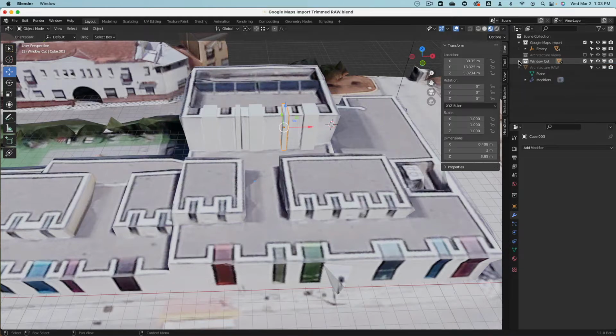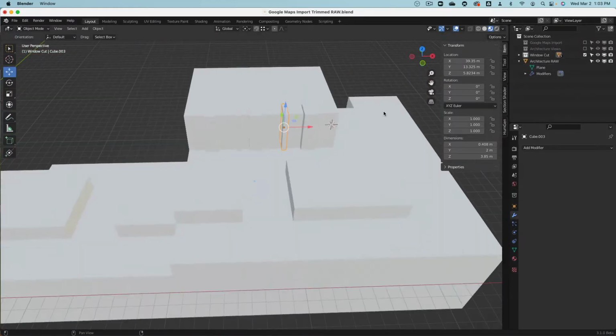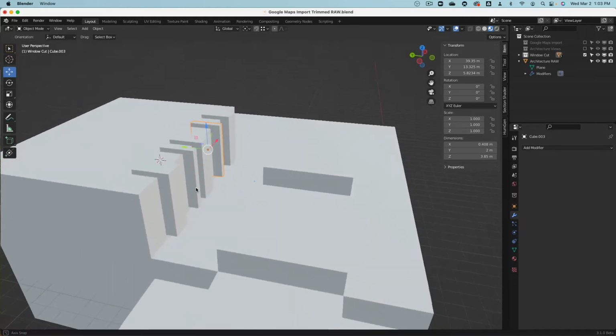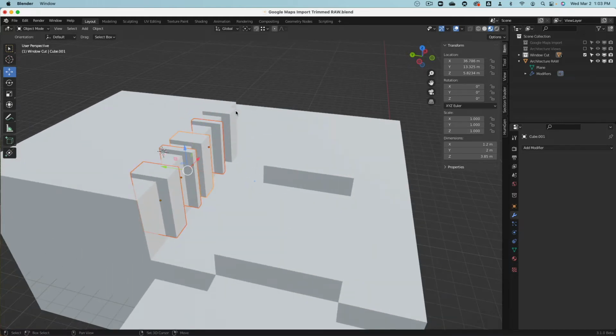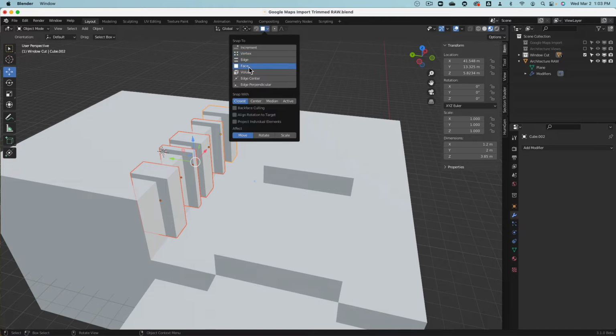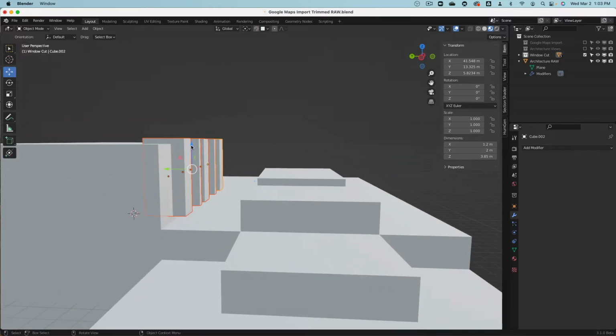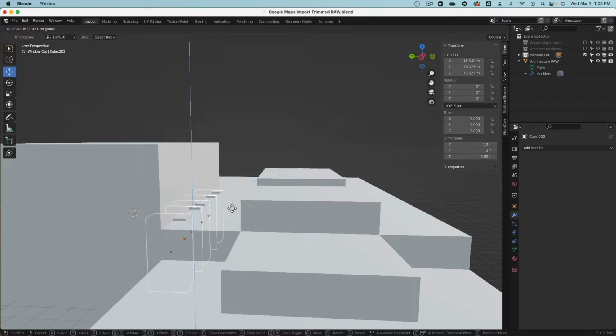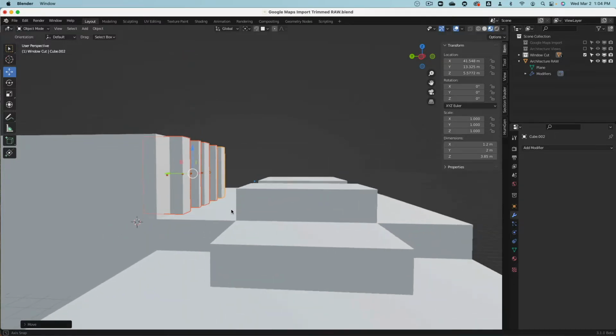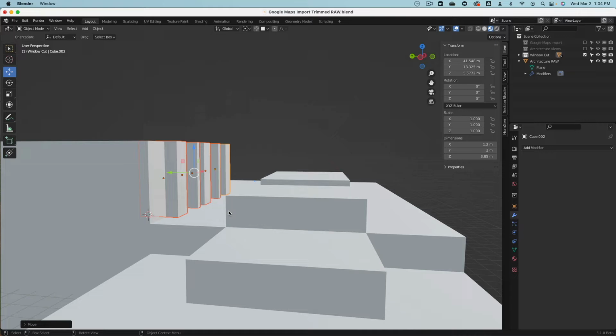Okay, very nice. So why do we do this actually? I can hide this. I can turn this on. Now I can, if I want to, select all these objects, turn on face select or snap. Sorry, move this up, move this down. And when I'm on this top roof face, hold Control key and you see how it snaps onto it. I would like them to be, however, not right on it, maybe a centimeter above. So G for move, Z for the Z axis, and 0.1 meters, which is 10 centimeters. Enter.